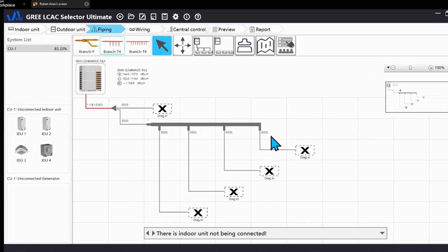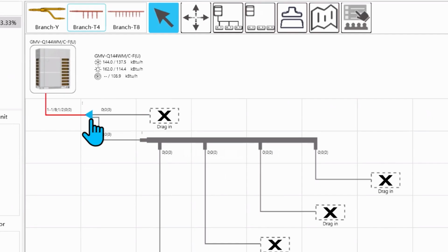Remember, as I mentioned before, this is only showing one direction. There is another one coming back. So let's talk about the ball valves for a minute for future use. Put the ball valve on there, but you also need to put a piece of pipe on there and cap it. Don't just leave the ball valve shut off. That's a good way to have a potential situation where you dump the whole charge in the building.